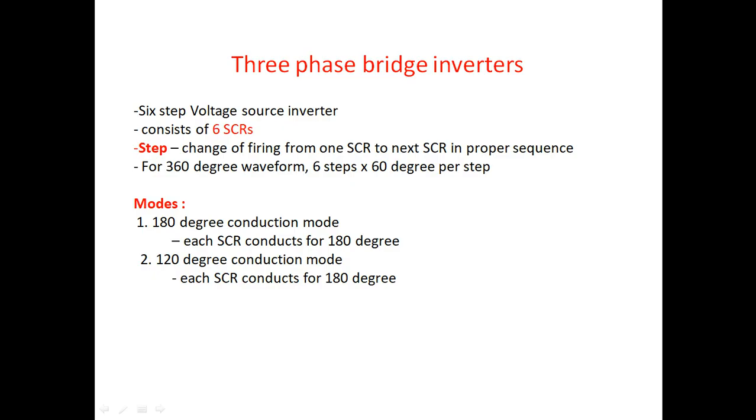The 180 degree conduction mode means each SCR will conduct for 180 degrees, and in 120 degree conduction mode, the conduction period of each SCR will be 120 degrees. So that was a typographical mistake. In 120 degree conduction mode, each SCR will conduct for 120 degrees.